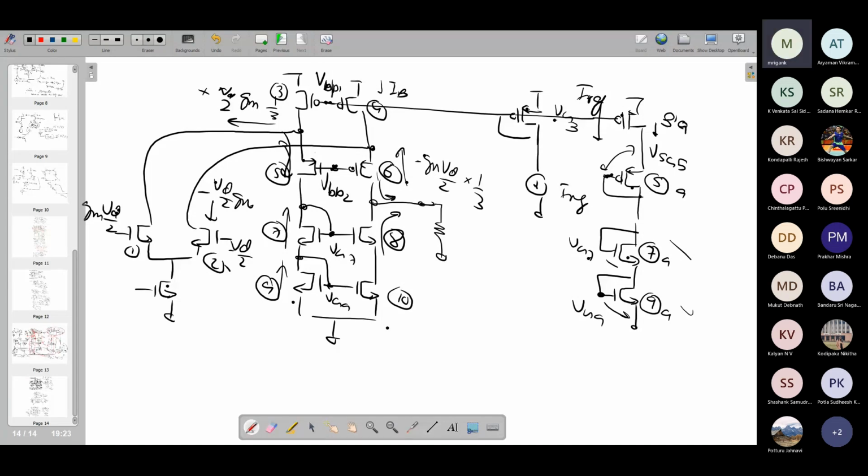Is that clear? So this is again a simpler scheme. We can go for reduced cascode swing, reduced cascode biasing, for better swing conditions. In this case, once again, you can see what the output voltage min required is. That will be VGS9 plus VGS7, right? So you have one VGS drop for M9, another VGS drop for M7, and that gives you the gate voltage of M7, and that is the same as the gate voltage of M8. So minus VT8 is the V out min.